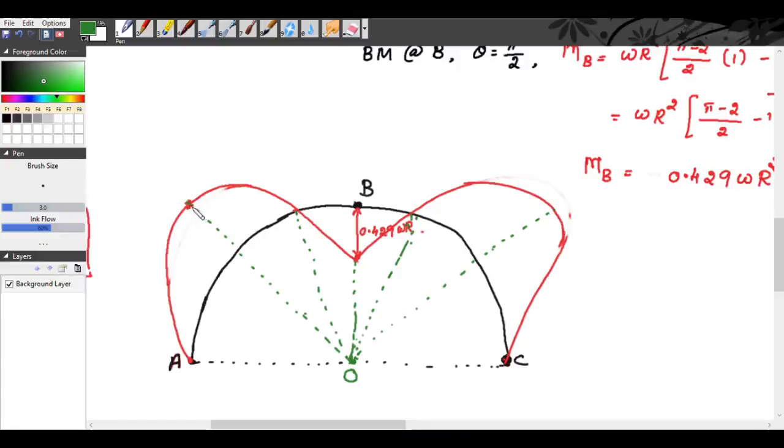Okay. So now we need to find this. This is our M max, maximum bending moment, and this is the point of contraflexure. That is, your bending moment changes from positive to negative. Positive and negative. So here negative and positive. Okay, now our aim is to find the angles. What is this angle and what is this angle? If you have found these two things, your problem is over for bending moment. Then similarly we have for twisting moment also.